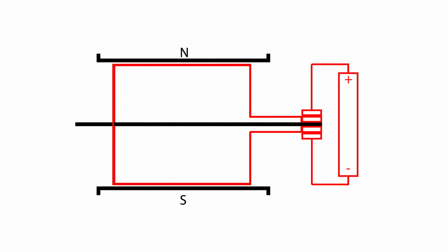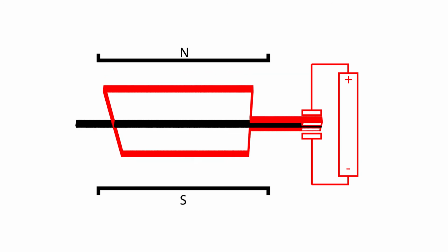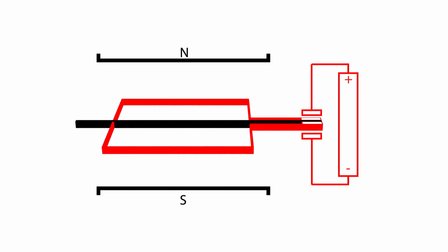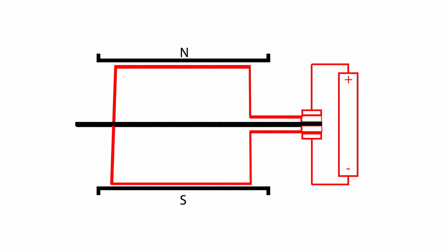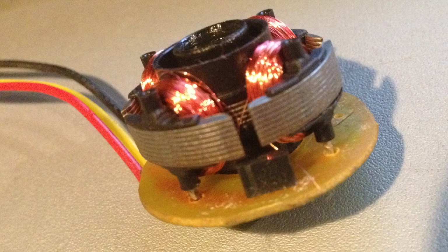The electric current would then flow in the opposite direction in relation to the rotor, because the brush is now contacting that side, again repelling it from the current position and attracting it to the next. So the axle will continue to rotate in the same direction until electric current is no longer flowing through the wire. This is a segment of a computer fan.